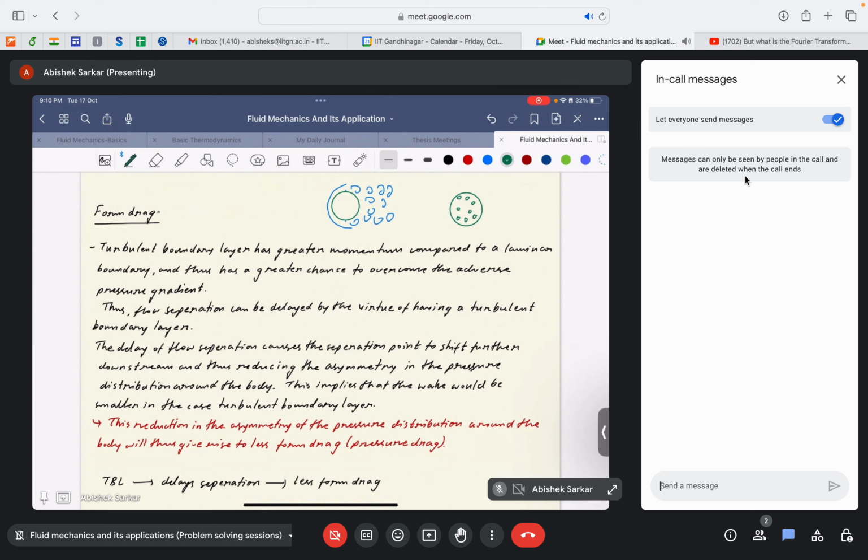These dimples trigger the boundary layer to make the transition from laminar to turbulent, so that the net momentum transfer across different layers of the fluid flow is higher. This high momentum transfer results in the flow staying attached to the surface for a comparatively longer time than the laminar boundary layer. So here you will observe that the boundary layer extends up to this point, and then the vortex shedding, or flow separation, takes place.